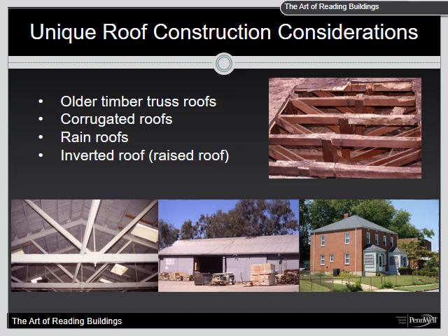Inverted roofs will always have a cockloft and necessitate evaluating for the presence of a fire. Due to the design of an inverted roof, the small members are underneath the roof sheeting and can be easily weakened by fire, which presents a notable hazard to roof personnel. As inverted roofs are generally older, expect multiple layers of roofing material on the roof.